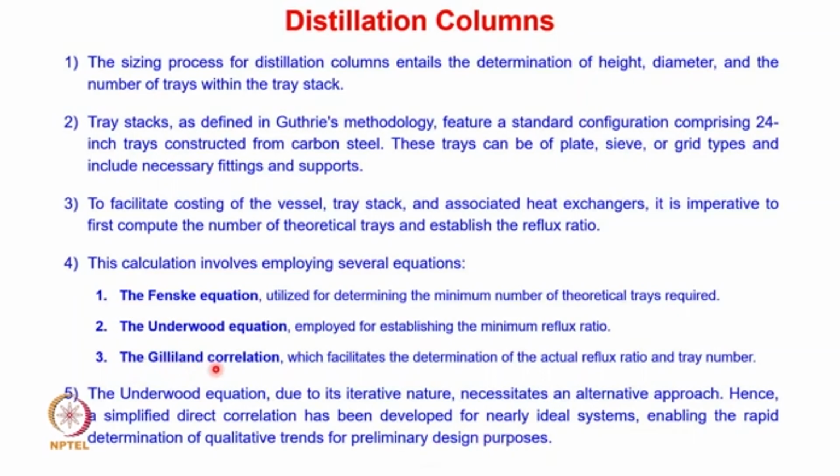The third important equation is, once we calculate the minimum reflux ratio and minimum number of theoretical trays required, we can use the Gilliland correlation and calculate the actual reflux ratio and number of trays. Okay.